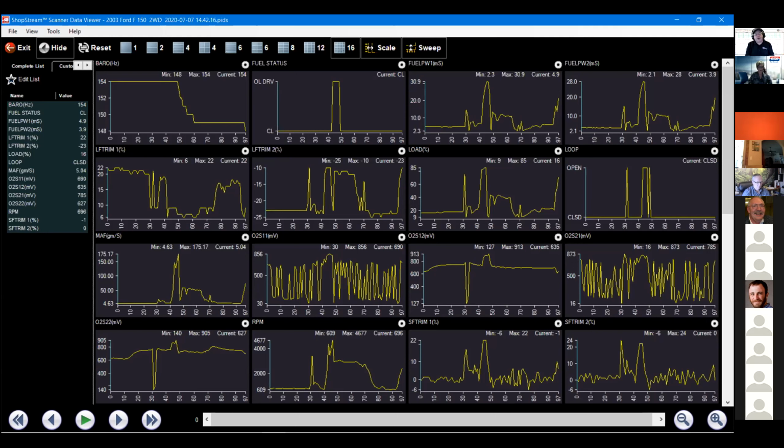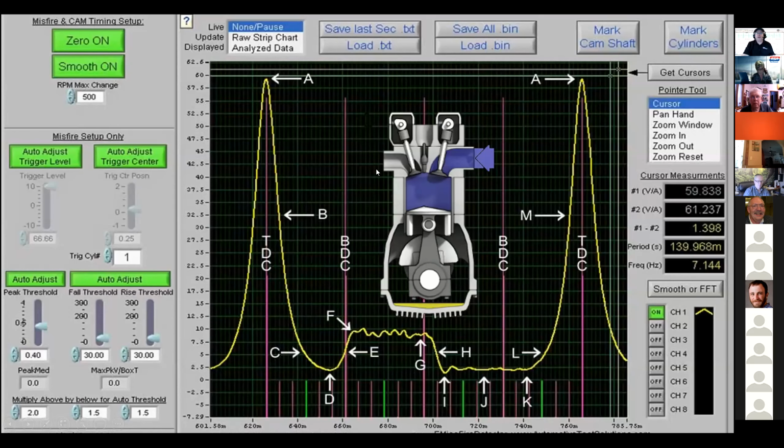So I'm still looking for the most efficient way, at least in my mind, to determine where to go. My scan tool data says, I think there's a breathing issue bank to bank. Then wouldn't it be smart, guys, to do a test with our lab scope that would give us as much information as possible? For example, this is the in-cylinder breathing.